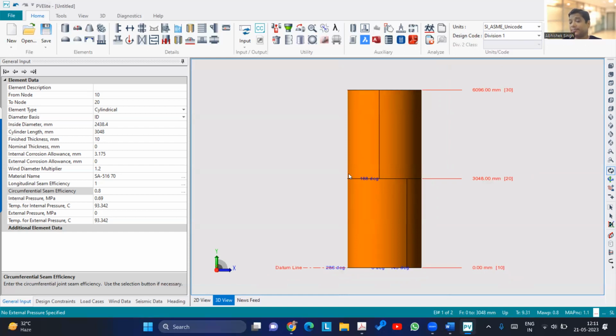Now let us see, only one seam is remaining. I have to do post-weld heat treatment, then I'll just cover this seam like this and do the heat treatment. I don't need to again insert the complete vessel because this is my target. There is a PWHT zone which has to be maintained, that width has to be maintained. And if I'm able to do that, I'll do only the heat treatment of that seam. I'll not insert the full vessel. Is it clear, Akash?